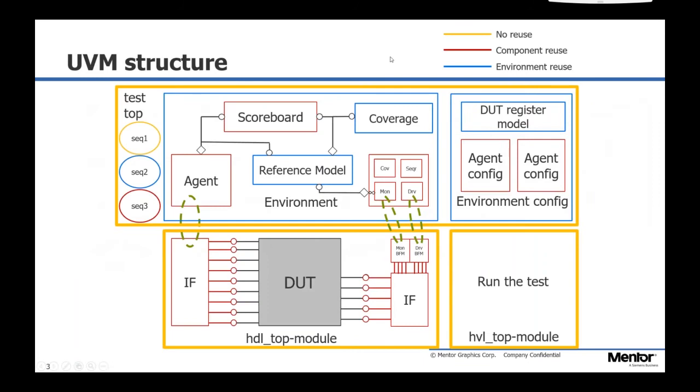So the UVM. UVM is a super powerful methodology for creating your test bench. The whole point of UVM is that it allows you to work at a much higher level, at a transaction level, so that your tests and scenarios are generated at a higher level, which means you can do more interesting things. There is randomization, which helps with uncovering bugs that you never thought about. So it's good for bug hunting. Lots of benefits of the UVM.